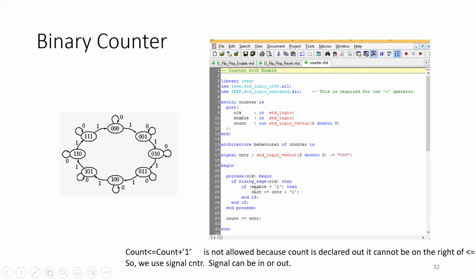I go back again. If there is a rising edge, I increment. I have this, it was 0. Now I increment it to 1 and I put the 1 to out. Now I go back, increment. This is a rising edge, so 1 plus 1 will be 2. I output 2, go back.